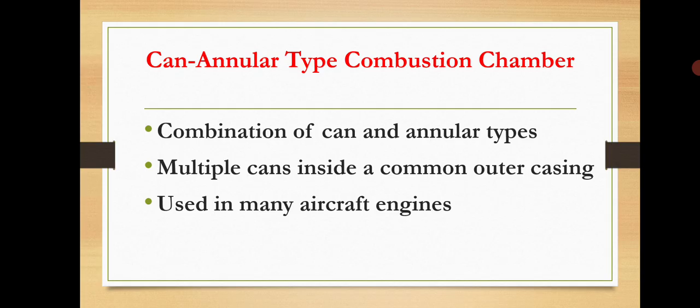It uses multiple individual cans arranged inside a common annular outer casing. It combines the strength of can type and the efficiency of annular type designs. Each can has its own combustion zone, but they share a common airflow system.